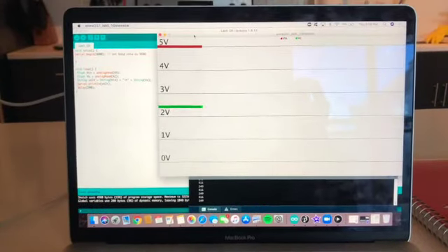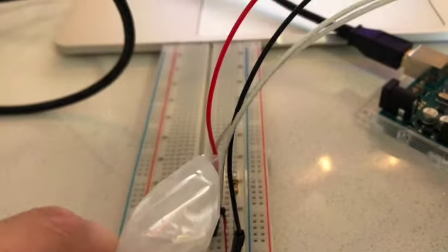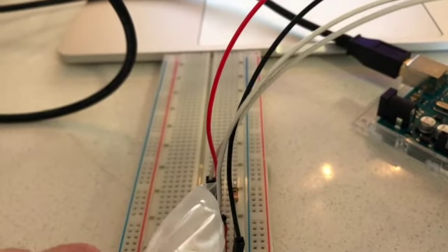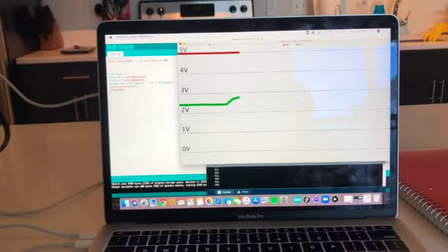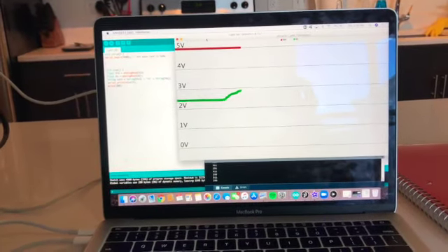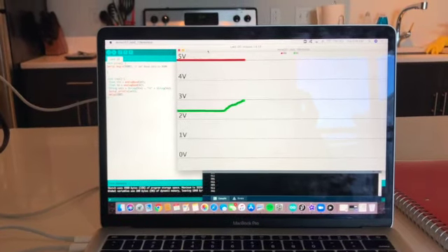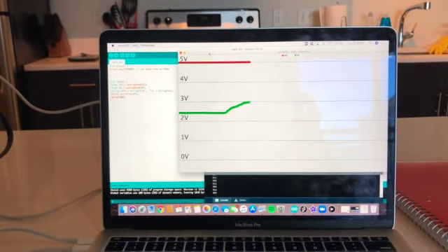And now, when I decrease the temperature with the ice cube, the resistance of the thermistor goes up, which makes the voltage output increase. I do believe the circuit behaves as intended, as there's a linear relationship between the cooling of the resistor, which makes both the ratio of the voltage divider and the output voltage increase gradually towards 5, and when it is heated, it makes both the ratio of the voltage divider and voltage output decrease gradually towards 0.